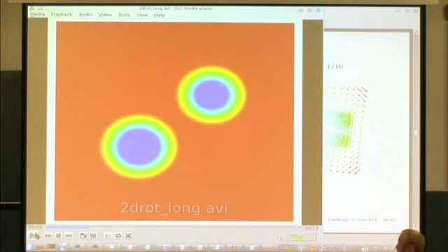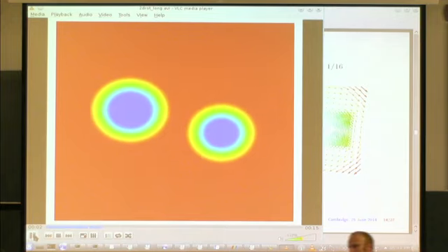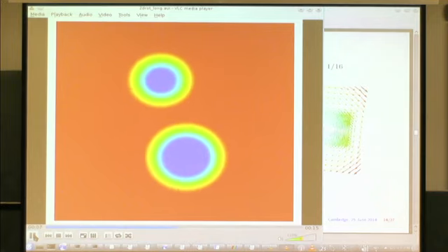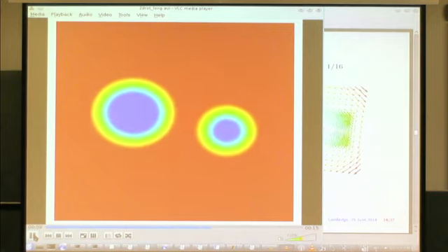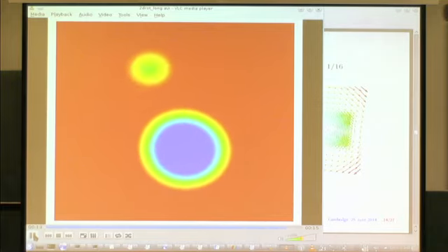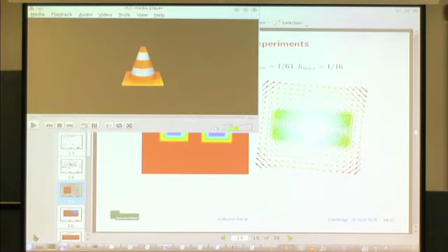There is a lot of work on the solution of advection equations where people want to minimize the numerical diffusion. Here we have no classical numerical diffusion, but there is the Cahn-Hilliard diffusion. And what will happen is that the smaller bubble will be absorbed in the big one. I used to show this as an example of non-physical behavior of the model.